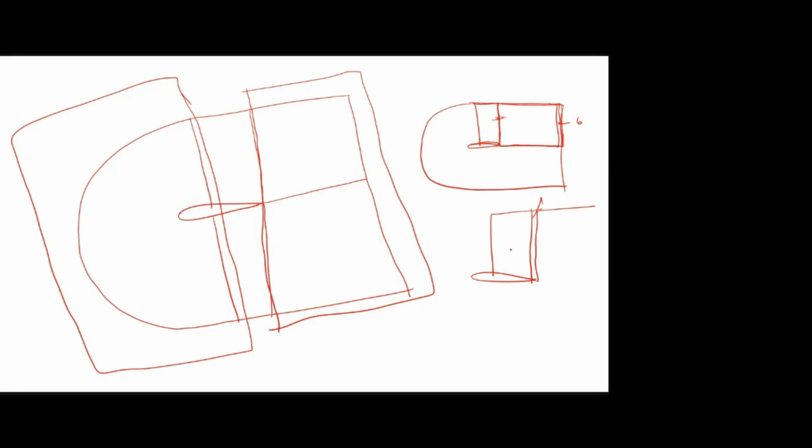Sir is telling that sometimes there will be two phases overlapping here. These types of issues some people will get if they try other methods. So there is a way to check it. After the IGS file, you import it again. There you can see the number of phases. Whatever, if there are 5 phases, there also it will show 5 phases. If it is exceeding or less than that, then you have to ensure where it goes wrong. That's what sir is telling.